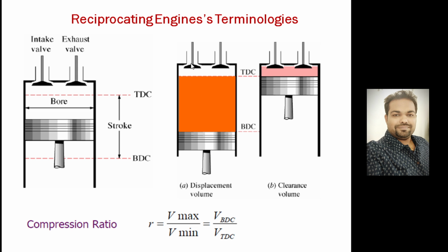All right. So if you look at this, when you are taking the air inside, your exhaust valve will be closed, the intake valve will open, air will come inside, and the piston will move down towards the bottom dead center. In the compression stroke, both the valves will close and the piston will move up. It will compress and reach near the TDC. Once it reaches near TDC, it has been compressed. Now your combustion has to be started. You can initiate the combustion with the help of the spark plug over here.